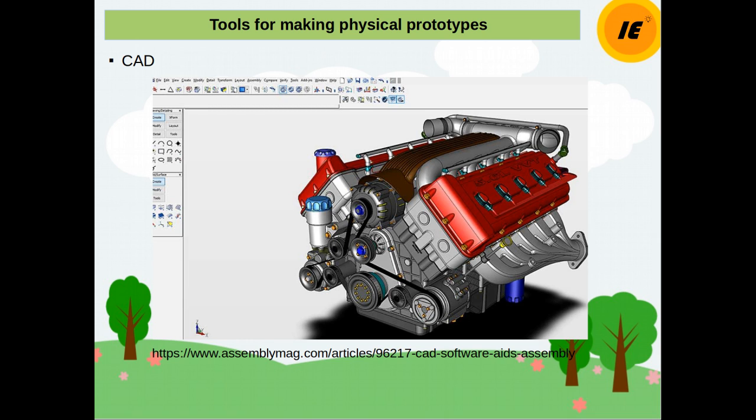So the advantages of 3D CAD modeling include the ability to easily visualize the three-dimensional form of the design, the ability to create photorealistic images for assessment of product appearance, the ability to automatically compute physical properties such as mass and volume, and the efficiency arising from creation of one and only one canonical description of the design, from which other more focused descriptions such as a cross-sectional view and a fabrication drawing can be created.